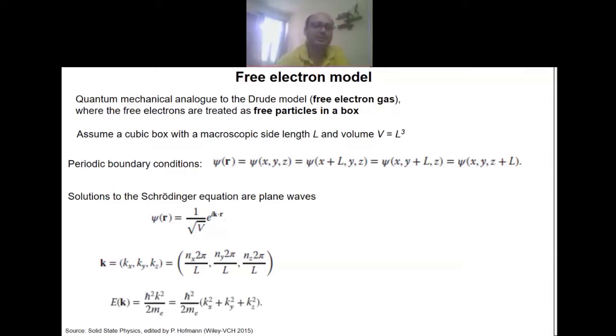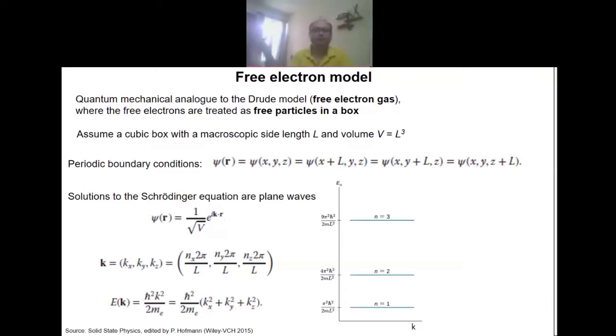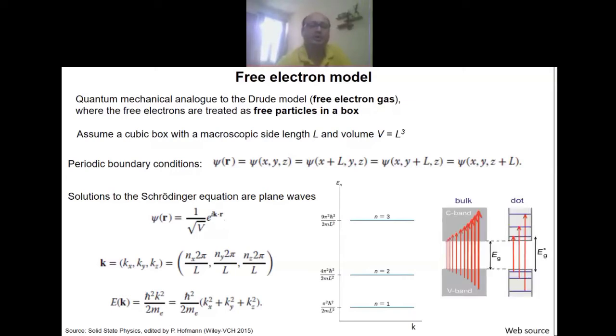Whenever you expose any metal to X-rays to get the diffraction pattern, we are seeing it in the Fourier space. That's why we have to think of the reciprocal space. That's called the Fourier space. The picture on the right hand side shows the reciprocal lattice distribution of this FCC structure.